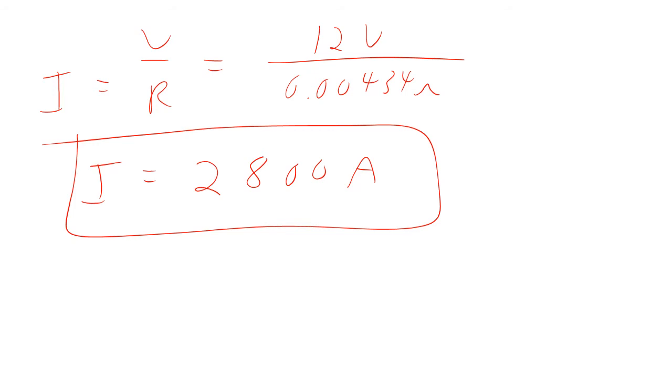At this point, there's something else that physically limits how much current it can put out. But still, this is a huge amount of current that's possible. So what will really happen is the battery will max out its maximum current output. But if we assume it did do that, what would be the power? It'd be I squared R, so if you plug that in, that's 34 kilowatts.